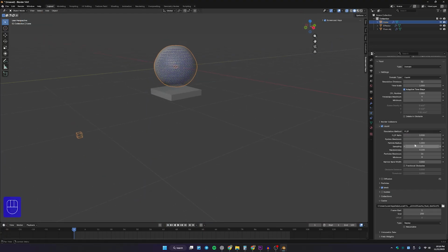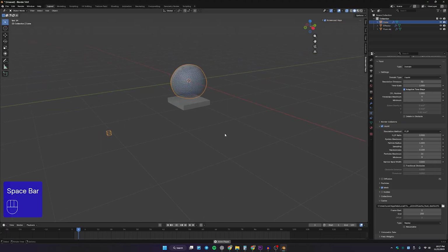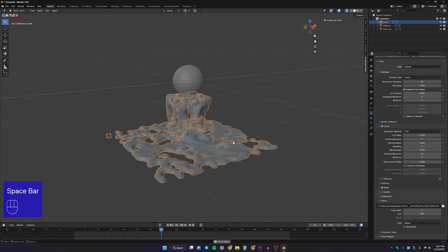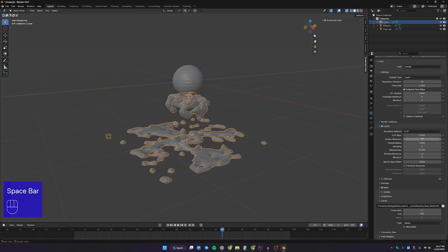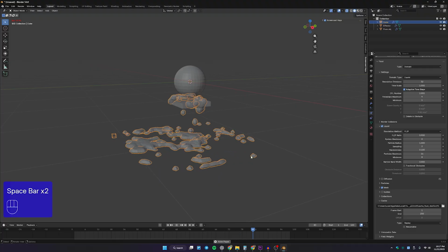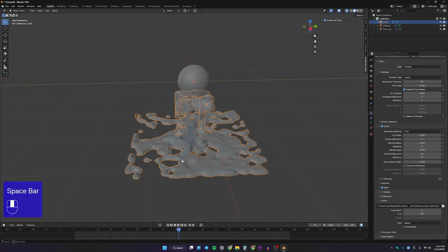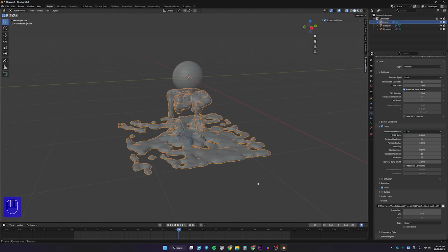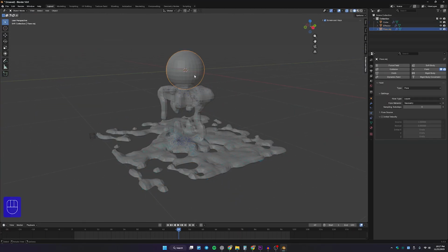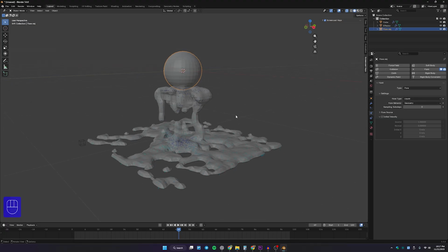Right. I'm going to go back, and now we have a couple of options. I'll talk about these things real quickly. We have the system maximum value, which means how many particles we have within our domain. Right now it is 0, which means we have unlimited particles. But you may think that we have a small number of particles, we could even count them. It is not that, because we have a geometry right here under the flow object, which means the domain is only creating a flow that fits inside the flow object. It is not continually creating.